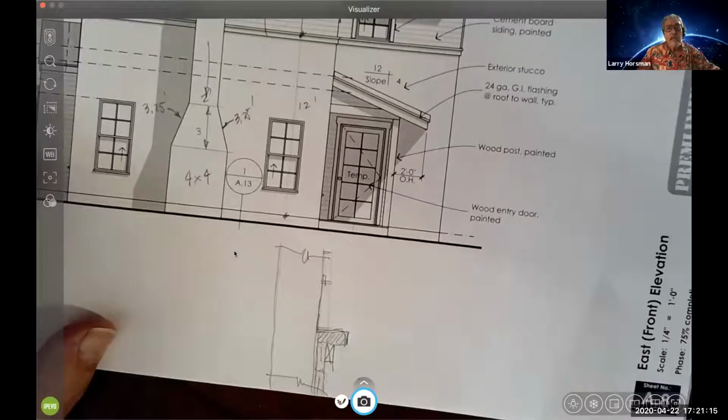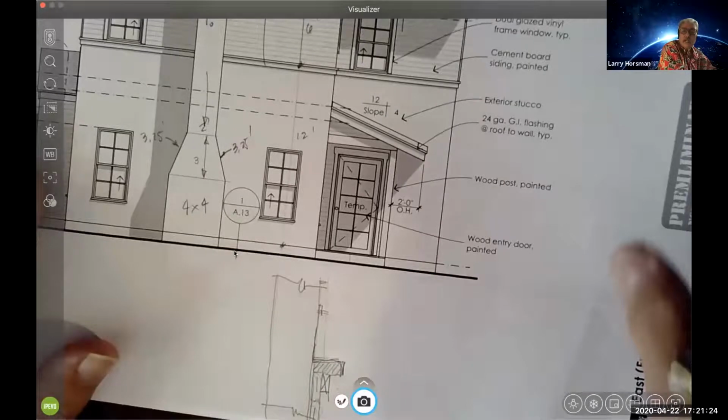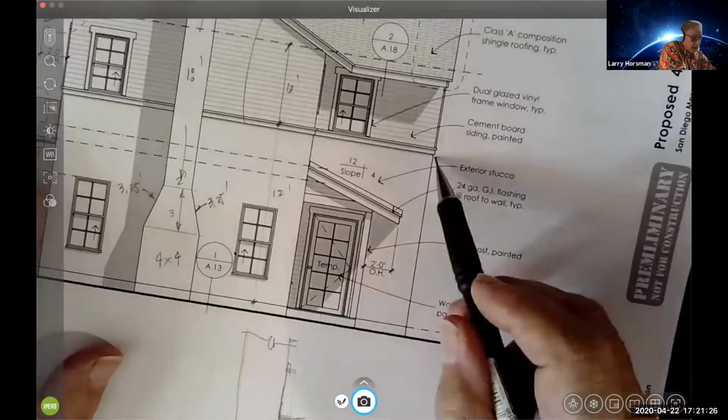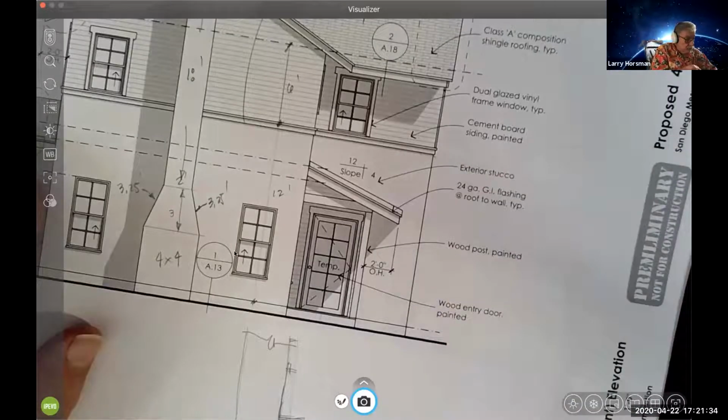In the elevations, if I see one, yeah, right up here, it looks like that whole thing comes out beyond the line of the finish. And so I'm just not sure how all that fits together, but I do know when you put a ledge like that, you're going to trap water. You're going to have water coming down there, and that's going to be a problem later.